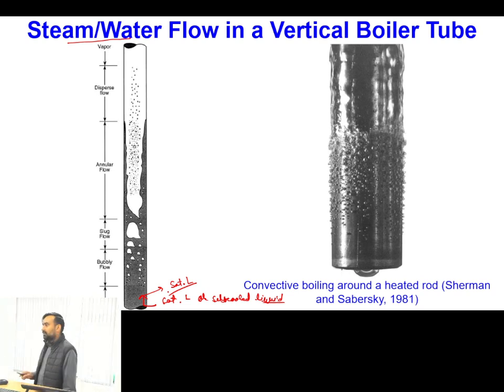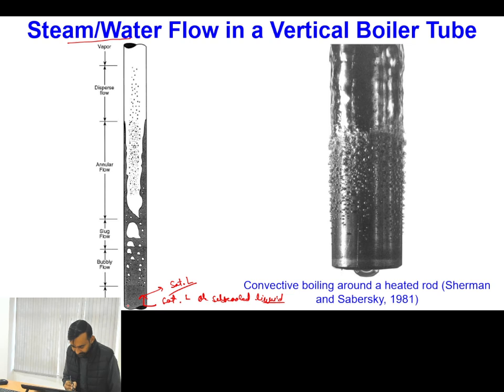Okay, is this point clear? And whenever this liquid is entering, initially what will happen? This liquid will try to gain some heat. Okay, and the heat transfer will be because of which regime? Natural convection or flow convection? Because this is flowing inside the tube, it will be because of flow convection.